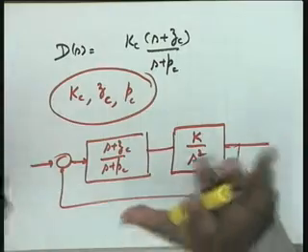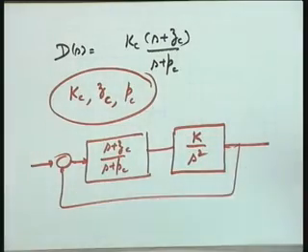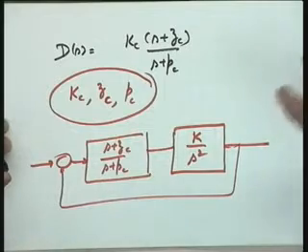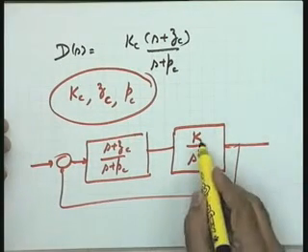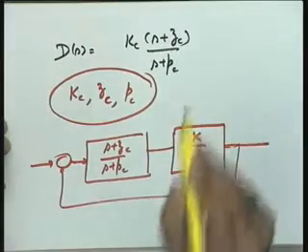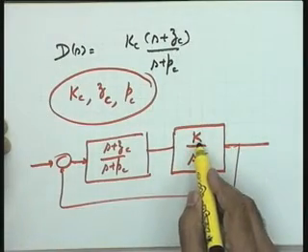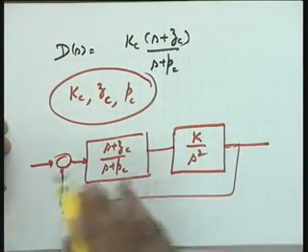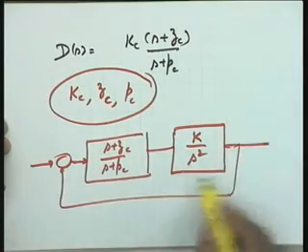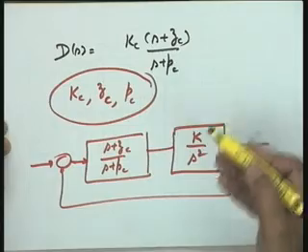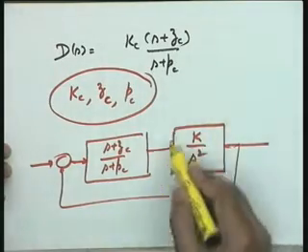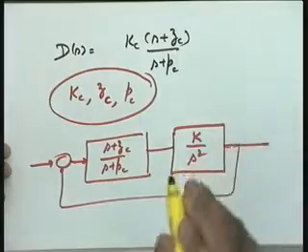You see, the point is this, that there are three parameters which are under your control. How do you implement those three parameters? How do you realize those three parameters? It depends upon the hardware. So when I put a K over here, it necessarily does not mean that you will make an adjustment in the plant. This K really does not mean that, though adjustment in the plant may partially realize your gain. For example, you require this K to be 100. You may realize it partially if some adjustment is possible.